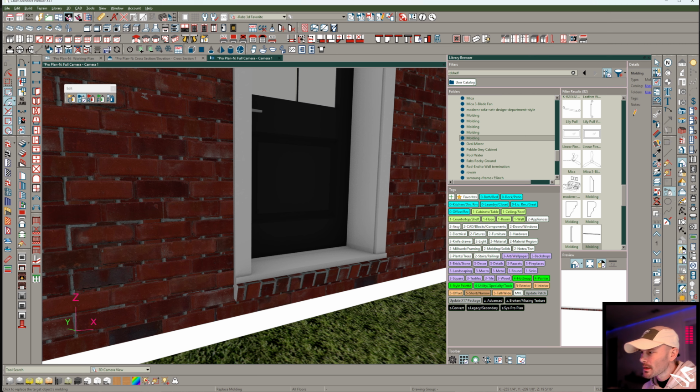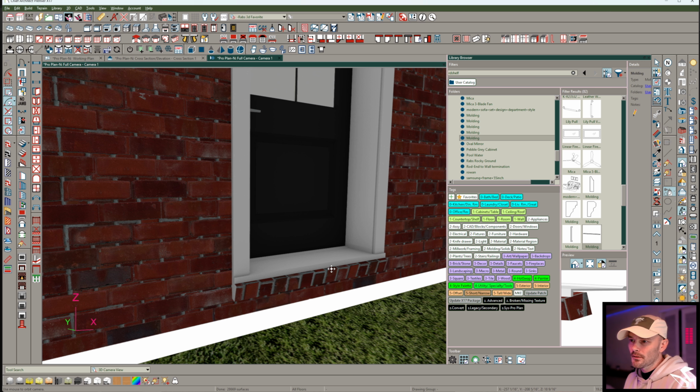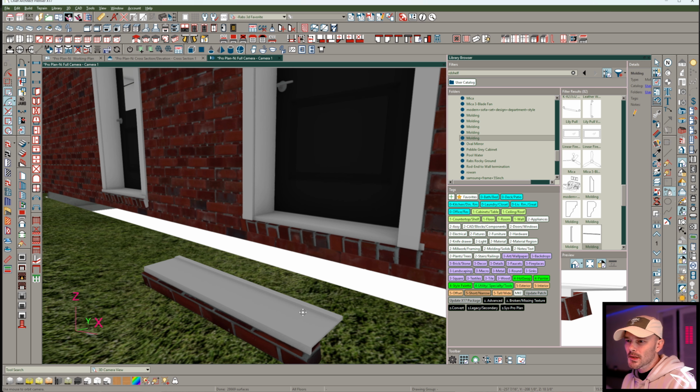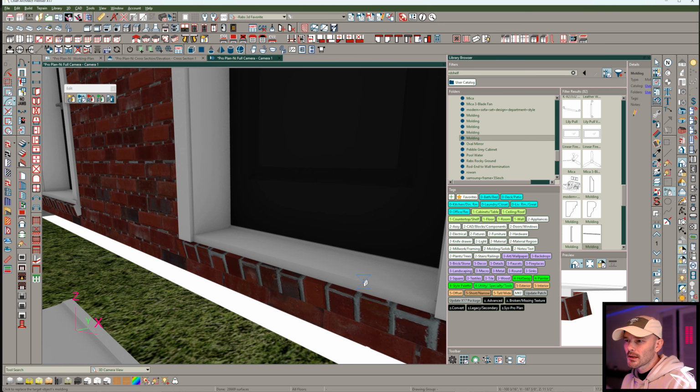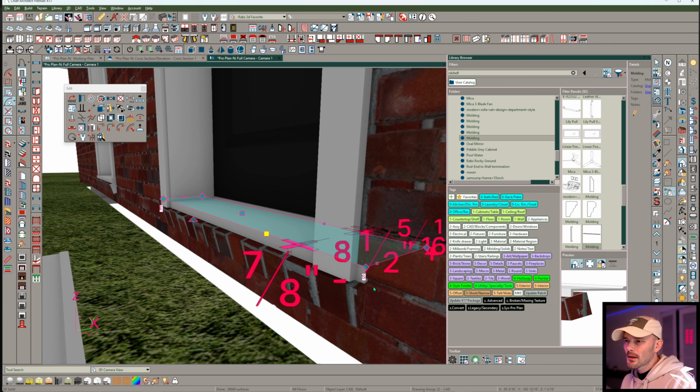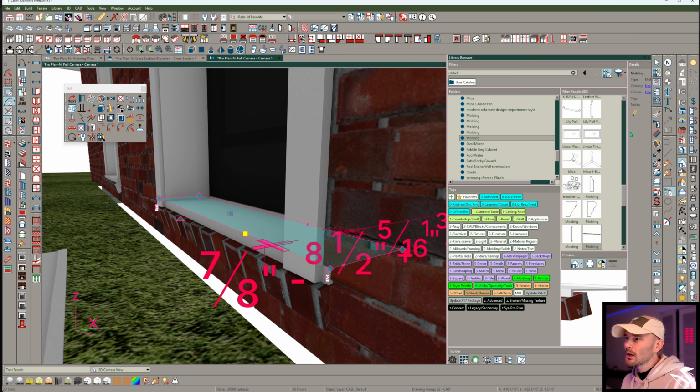Now I want to take a look at this molding again. Just one more look at this, to try to understand why it's just automatically filling in that section with white. That's so curious to me. So a potential solve of this, if I can get back to all the same settings somehow, is let me take this profile and I'm going to explode it. And I'm going to just kind of cheat. Because this is a solid, we can explode the 3D solid.